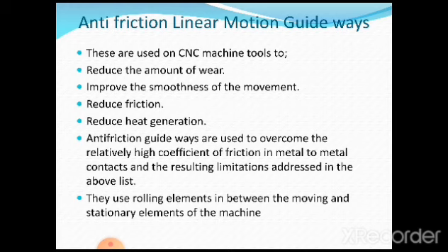Okay. The guiding element prevents the rollers from falling out and sliding against each other. So whatever element is provided as a cage, it will not allow the rollers to come out of that particular predefined path. That is what he is telling here. Also, the guiding element assists in smooth return of the rollers to the loading zone.